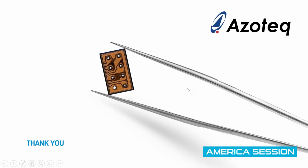How about calibration? Is it done during manufacturing? The design is calibrated during the design phase. So we follow a procedure where we say it is verified by design. So the IC, once it's properly designed and the correct thresholds have been selected during the design phase, those thresholds can be used throughout the lifetime of the device.